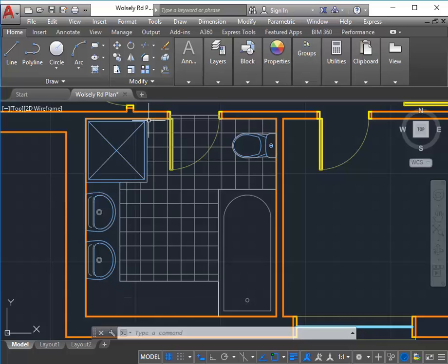So then, I won't show you the last thing, but there's one other important thing that you should have in all the construction drawings for your bathrooms to show the drainage. So do you know what that looks like when you show the drainage in a bathroom like this? Oh, the drainage. So, exactly, yeah. So the floor waste should be there, and then you should show a line of fall to that as well. You can add that in afterwards.